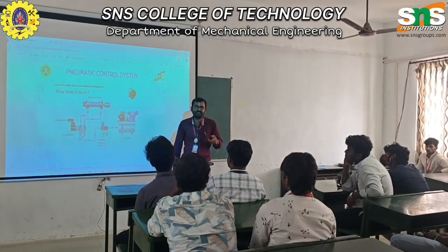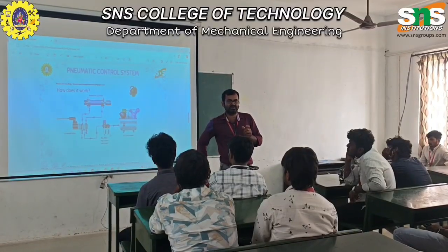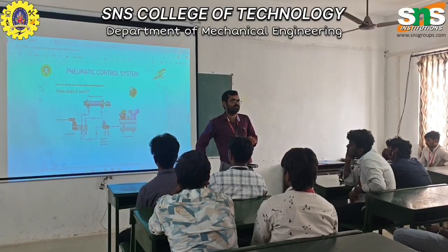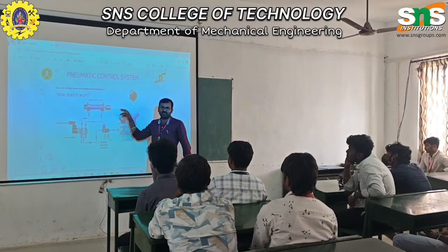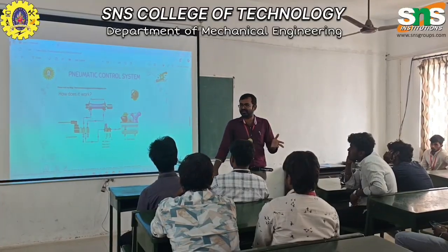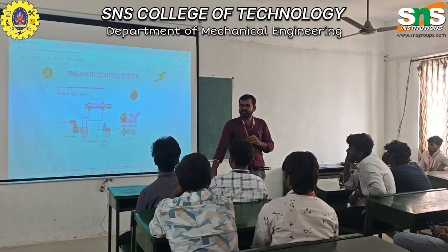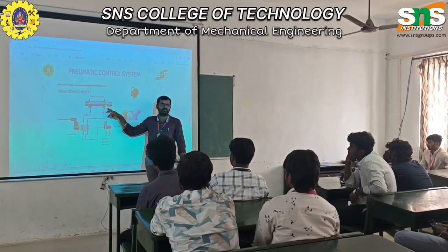Already you know the concept of single acting and double acting cylinders. A single acting cylinder has only one inlet port. We give the supply to the inlet port and automatically the piston moves in the forward direction. With the help of a compression spring, the retraction is taken care of. In our double acting cylinder, we have two ports. This is the inlet port and another one is for the